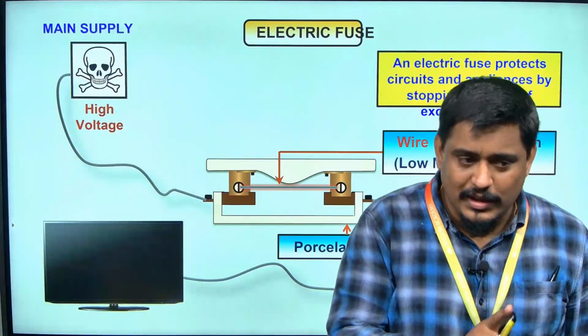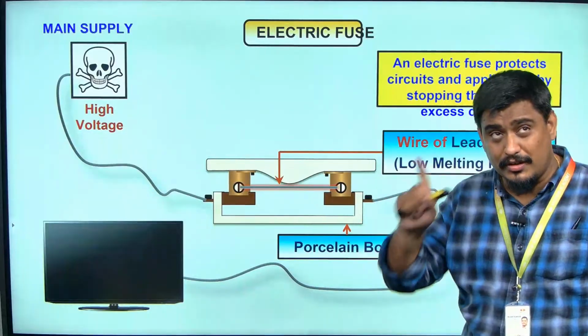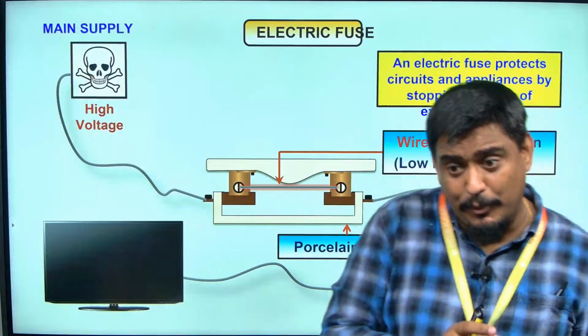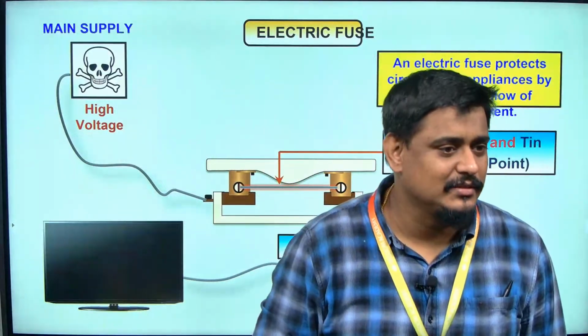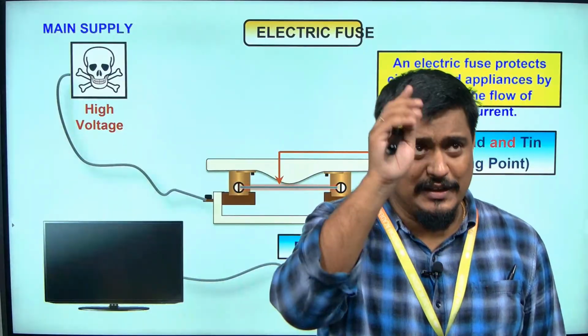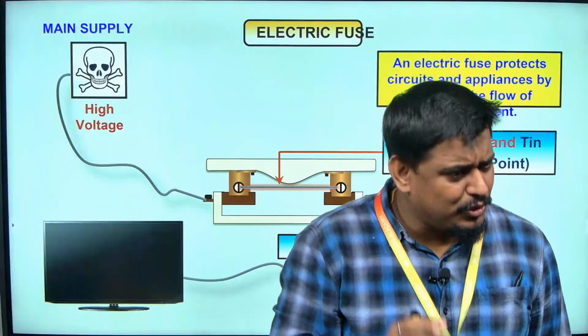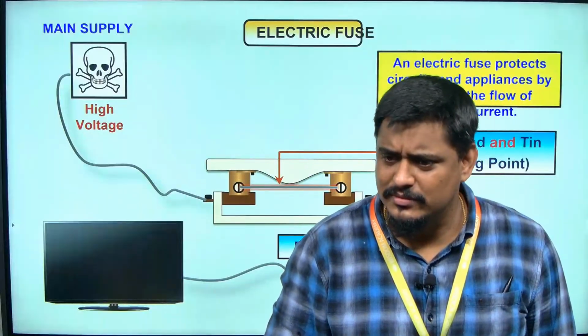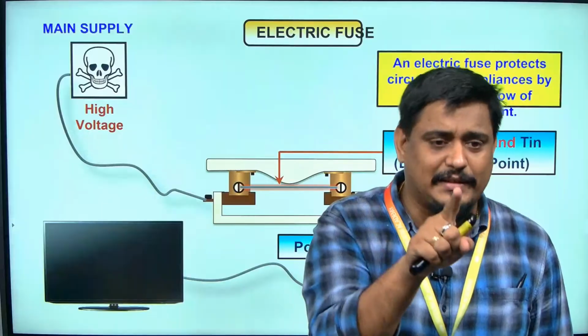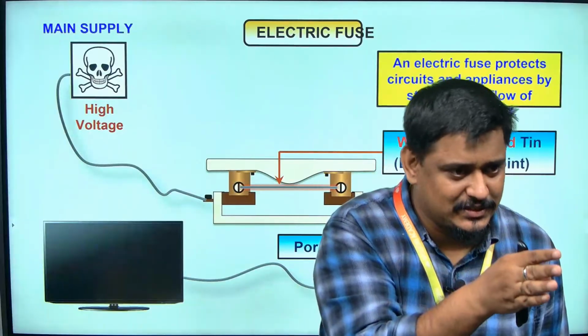Now, if I want to put a fuse for that, that is light. And if I put a fuse of 20 ampere rating, then what will happen? Excess current will go inside, isn't it? If it is working at 5 ampere, then I can put some 6 ampere fuse. Are you getting what I am trying to say? Because if anything goes beyond 6, it will melt. Up to 6, it will allow to pass.